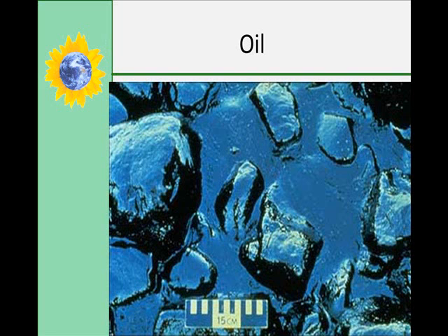Oil is usually recovered by drilling wells through a non-porous rock barrier that traps the oil. In general, about 30% of the oil trapped can be economically recovered by pumping. Secondary recovery can remove about another 10% by flooding the well with high-pressure water or gas. Another 10% can sometimes be recovered with tertiary methods that heat the oil to scrub it out. About half of the oil is still left trapped in the rock. Oil producers are continually seeking economical ways to recover more of this oil.